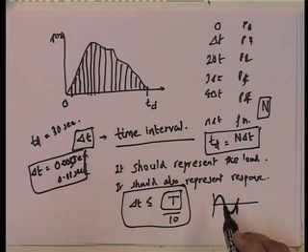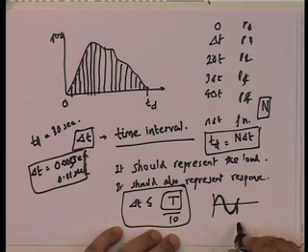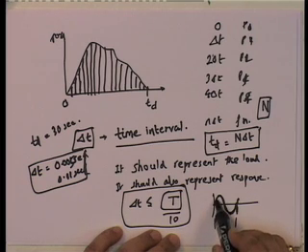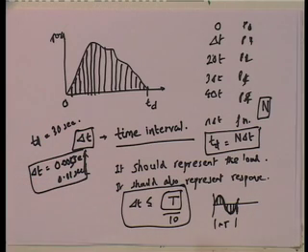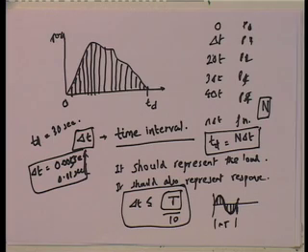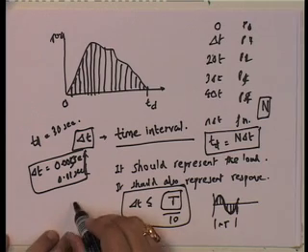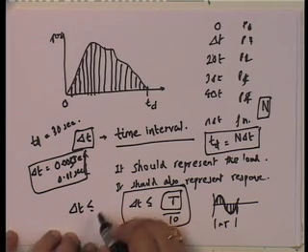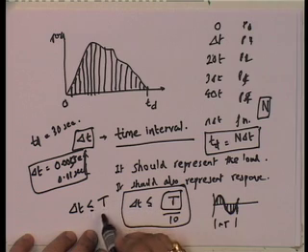With a single degree of freedom system, one cycle of response is T, and we should at least have 5 representations within it. This used to be the old way of looking at it. It is no longer valid. This is required for stability for some numerical methods, but typically delta t should be a significant number.